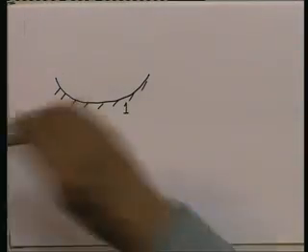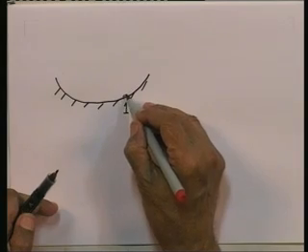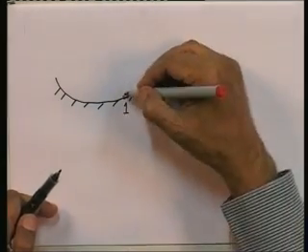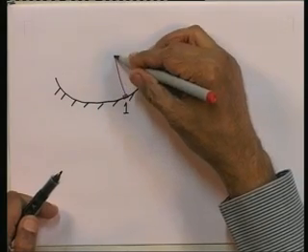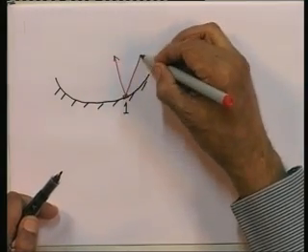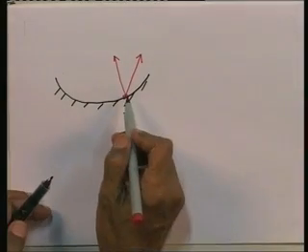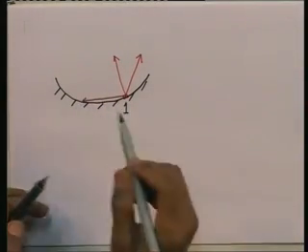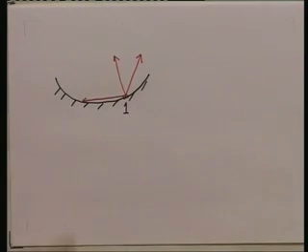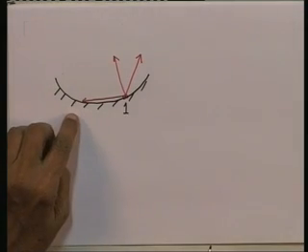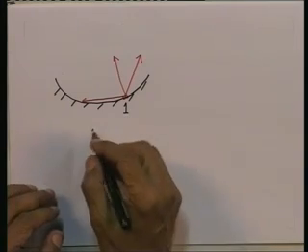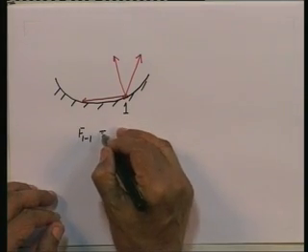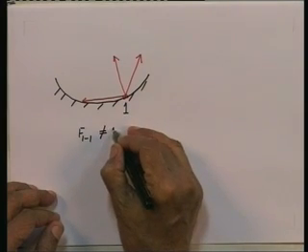It is obvious now, if I take some element on this surface, then some of the radiation which is emitted, radiation is emitted in all directions of a hemisphere, but some of the radiation emitted is obviously going to come back to the surface itself. Okay. So, this is a case because of the surface being concave, it follows that F1 to 1 is not equal to 0.